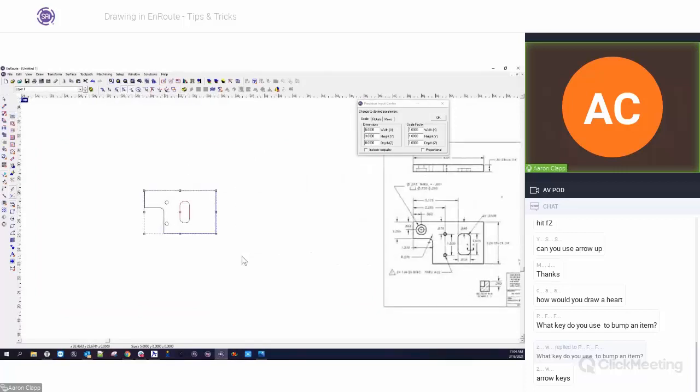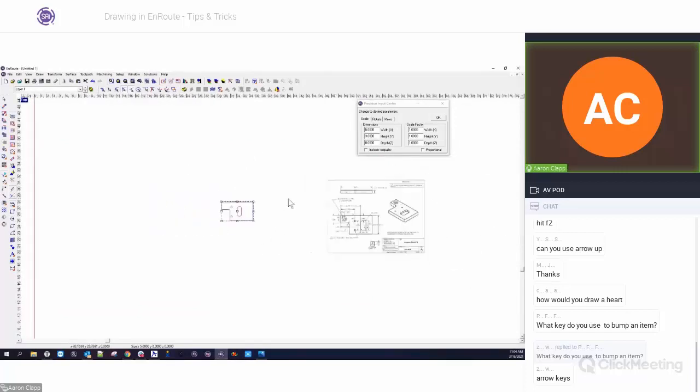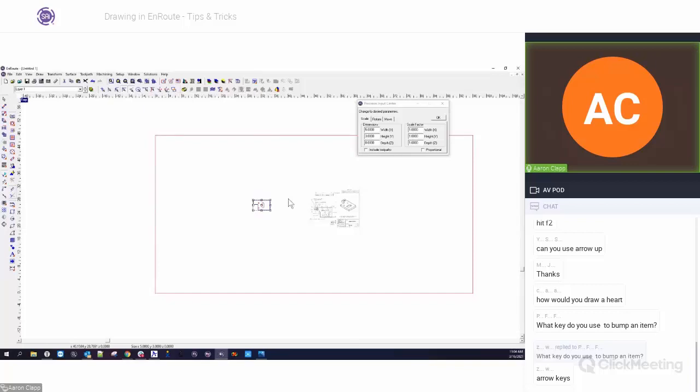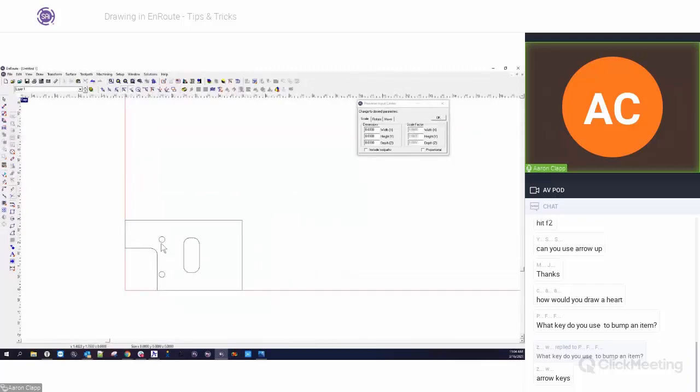I can grab my drawing and just hit. Now, if you have a keypad, you have to have the number pad for this. But if I hit Control-1, I can snap this right to the corner. And so this will put me right at 0, 0. And then I can design and move and change everything in regards to an absolute coordinate mode.